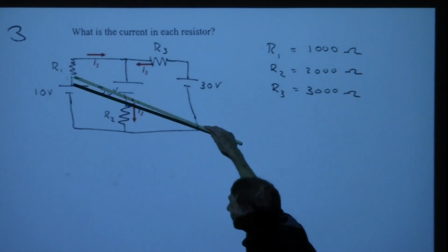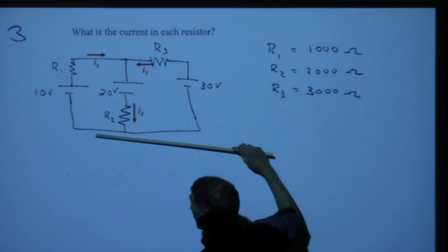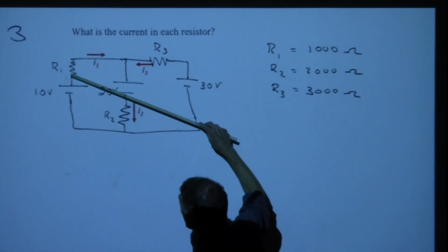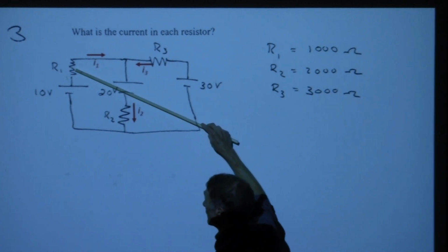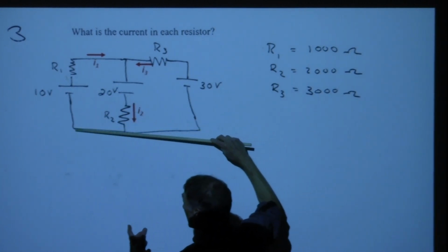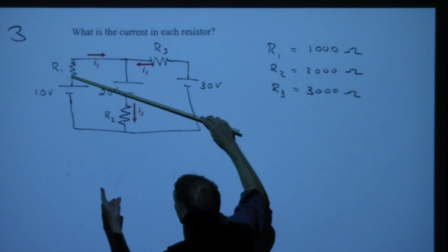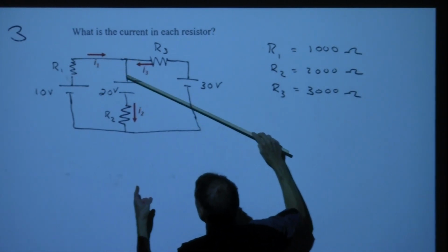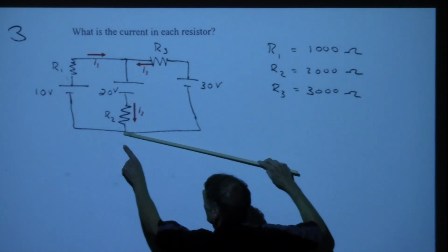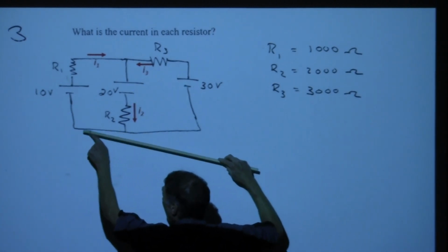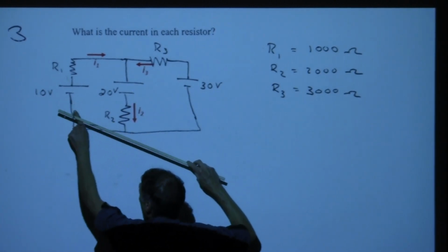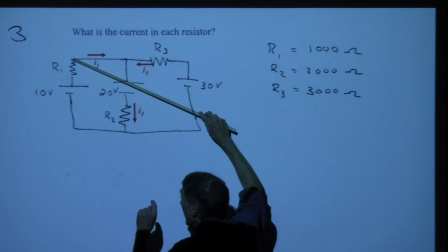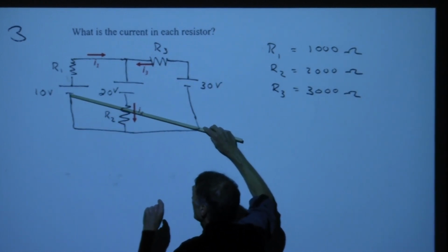This I1 covers the whole thing. These two elements, the battery and the resistor, are connected in series. So what's flowing out of the battery here, I1 is going through the resistor. It's coming back. It's going to split. Ultimately, I1 has to come back into the battery. Whatever leaves the battery on this side has to come back into it on this side.